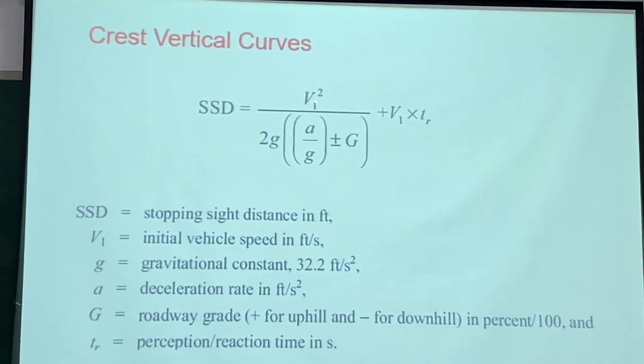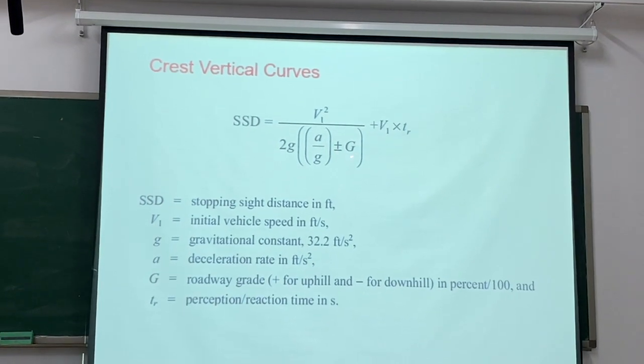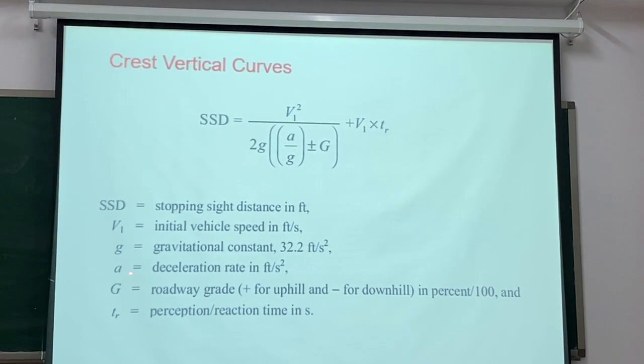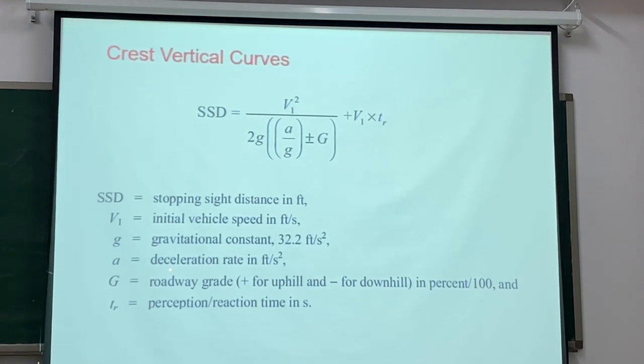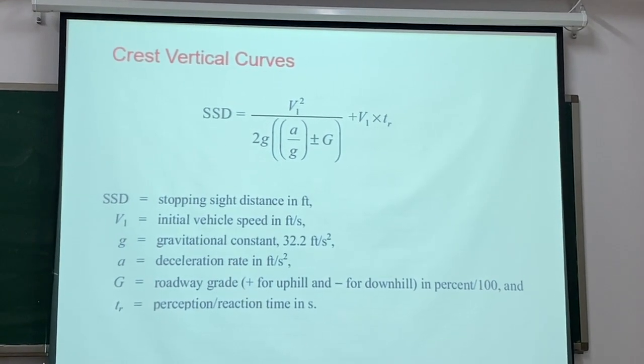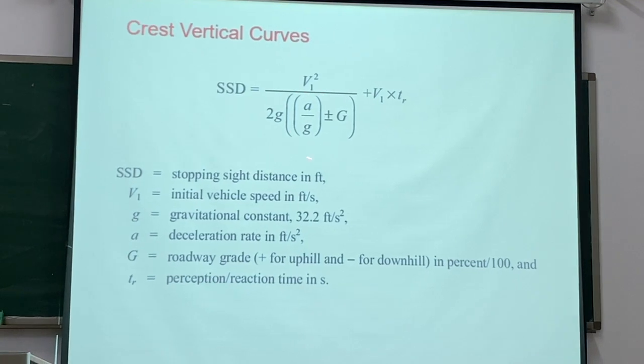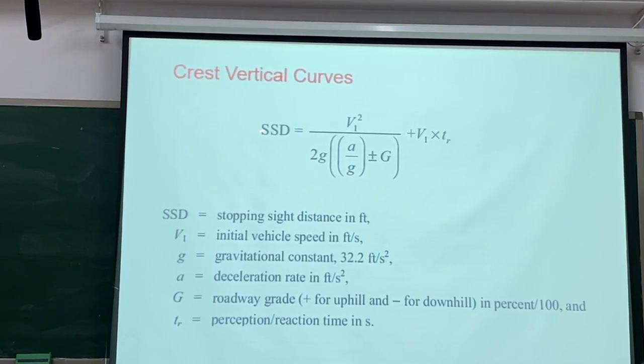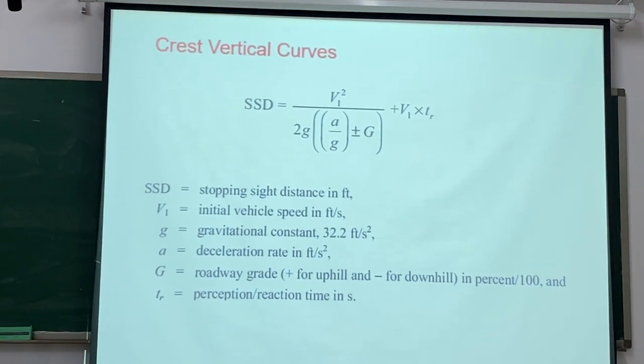We know V1, g, PR and a, the deceleration rate. We can use these equations to calculate SSD.